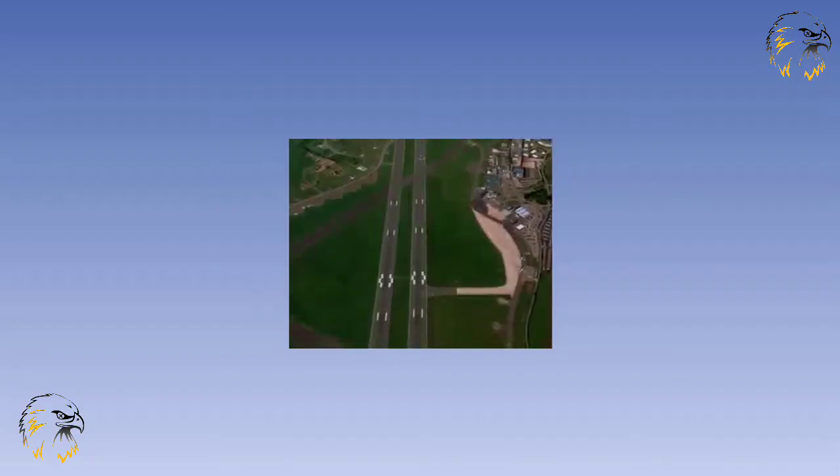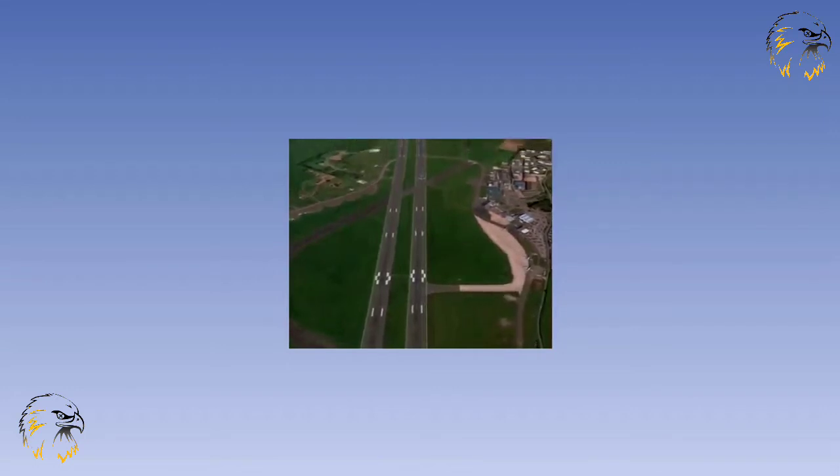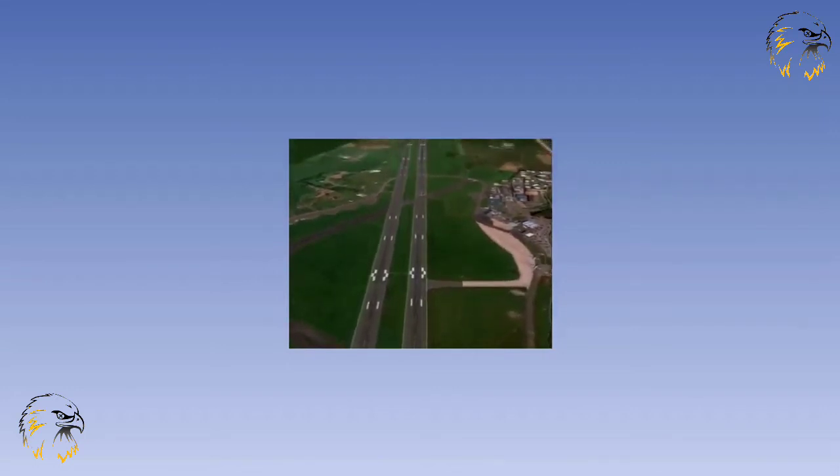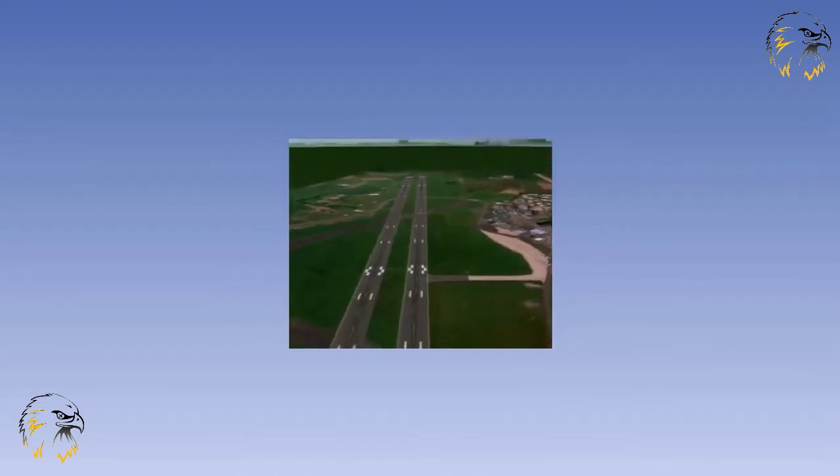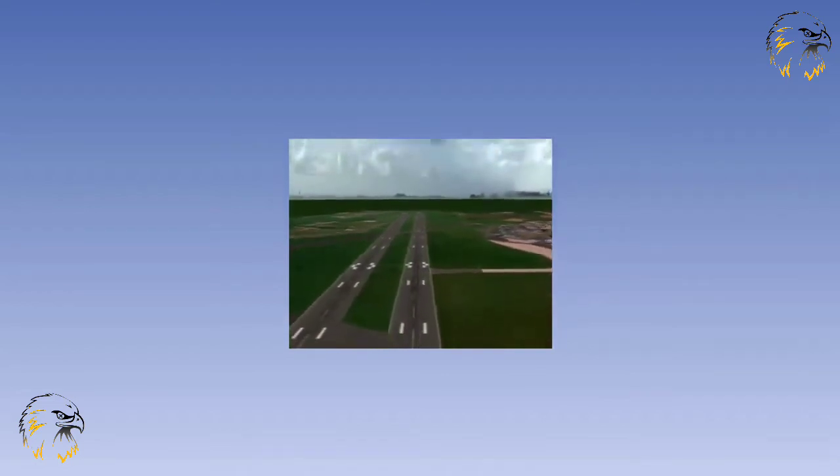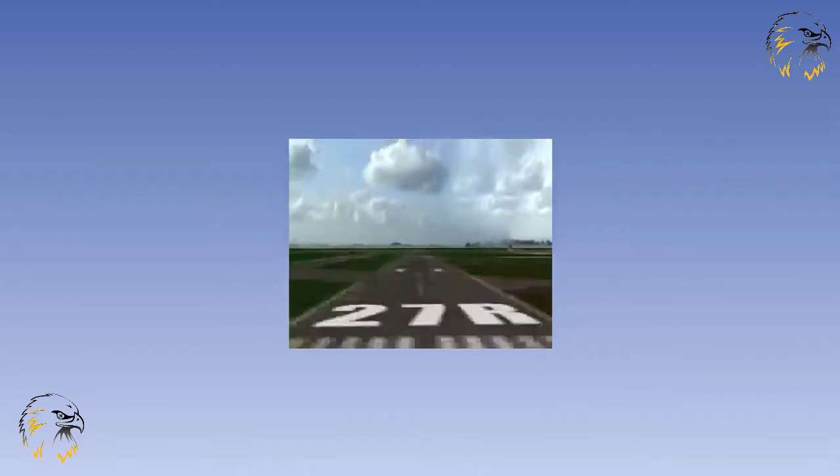The need to increase utilisation of aerodromes that handle IFR traffic in IMC can be met by the use of parallel or near-parallel runways. An aerodrome already having dual parallel precision approach ILS or MLS runways could increase its capacity if these runways could safely be operated simultaneously and independently in IMC.